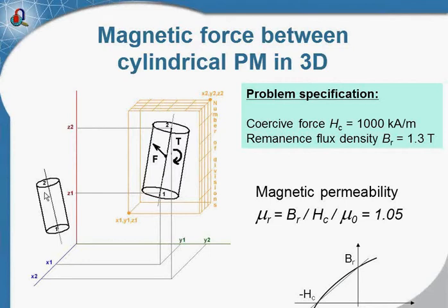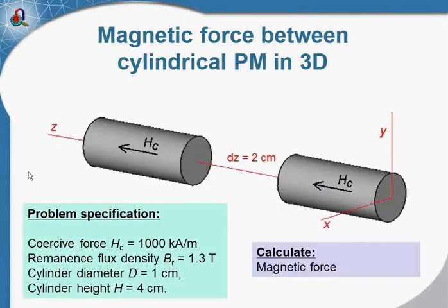First we calculate the magnetic field produced by the first magnet. Then we calculate the magnetic field produced by the second magnet. And then we can find the vector sum of both fields. This approach is implemented in our free tool. Let's take a look at a practical example. There are two coaxial permanent magnet cylinders. The cylinders are magnetized along the axis of rotation. In this case we can simulate in QuickField using the axisymmetric formulation.